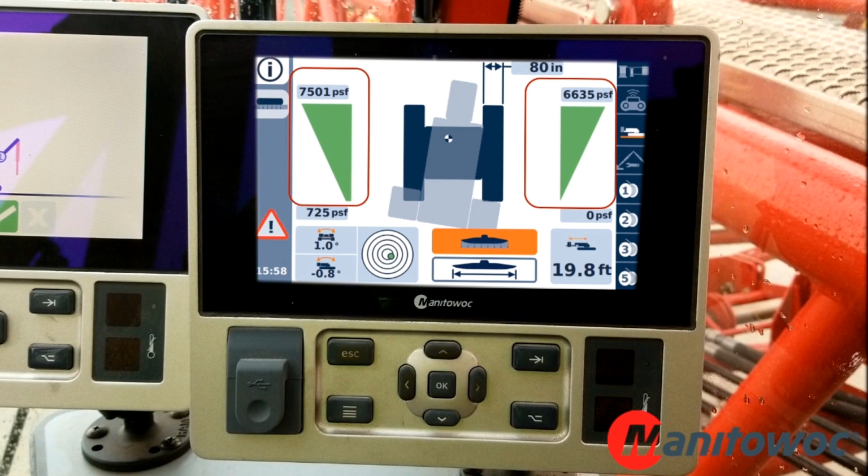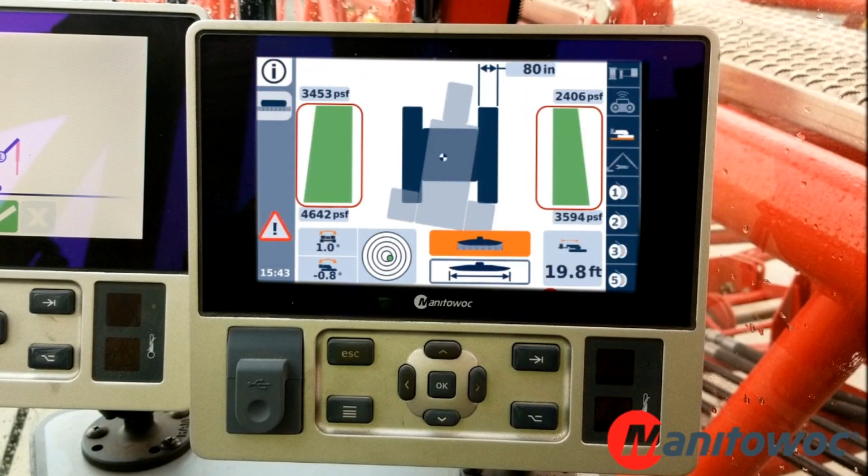If the ground bearing distribution is such that one or more corners are not taking any load, the number in the box will show 0, and the trapezoid will turn into a triangle, where the length of the side of the triangle along the crawler represents the contact length. For example, if the theoretical contact length is 50% of the total crawler length, the side of the triangle adjacent to the crawler will only be half the length of the crawler.